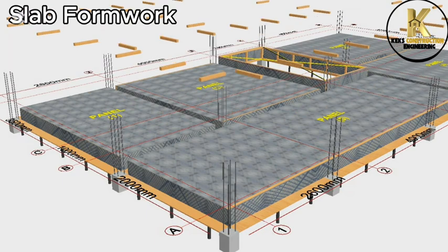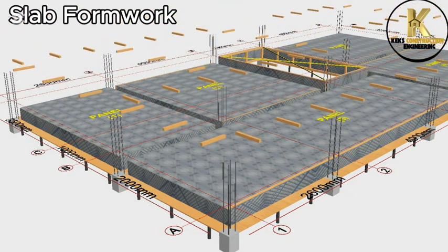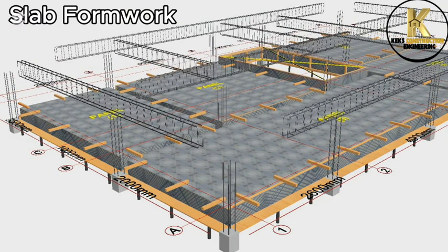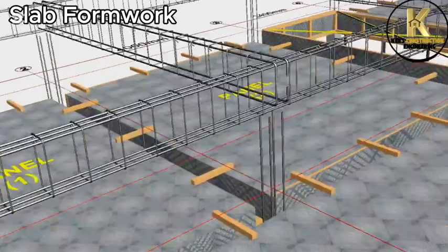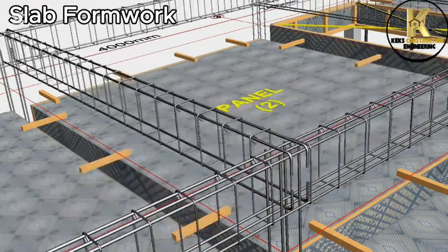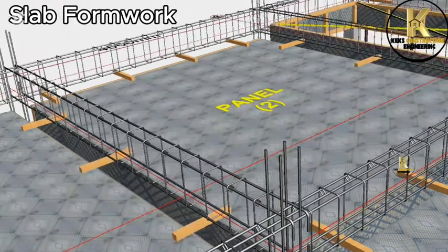These short woods are placed temporarily to stand the beam reinforcement so that they can be fixed, aligned, and properly inspected before lowering the reinforcement into the formwork. With this method, you can easily make corrections on the reinforcement without wasting time and extra money.